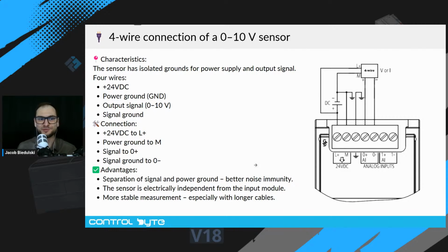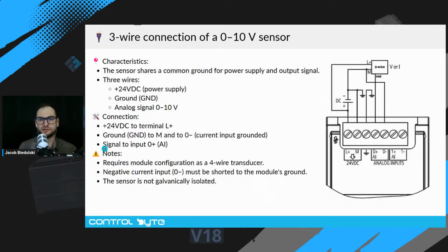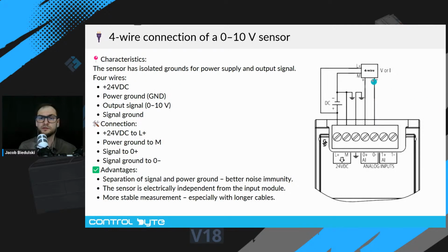But as you can remember, in industrial practice, we use mainly 3-wire connection because it is easier to implement, and 4-wire connection is more expensive when it comes to transducer and electronics. So if we go to, for example, Turck catalog, there will be no such sensor regarding voltage signal. The standard signals are mainly 3-wire connections.